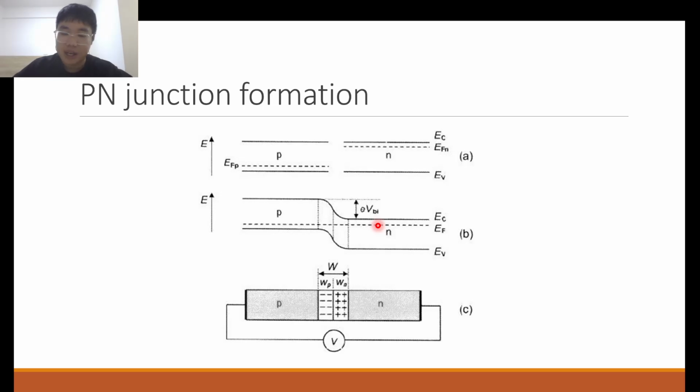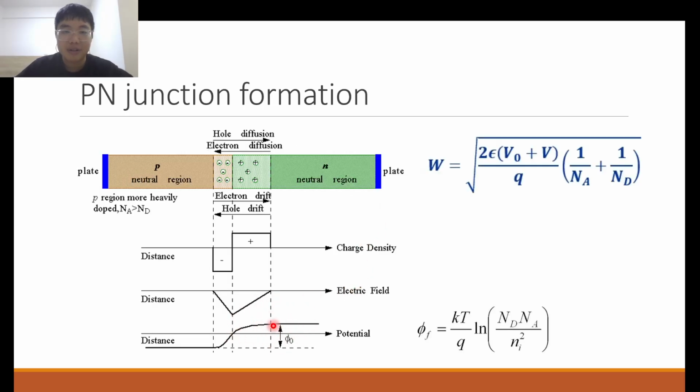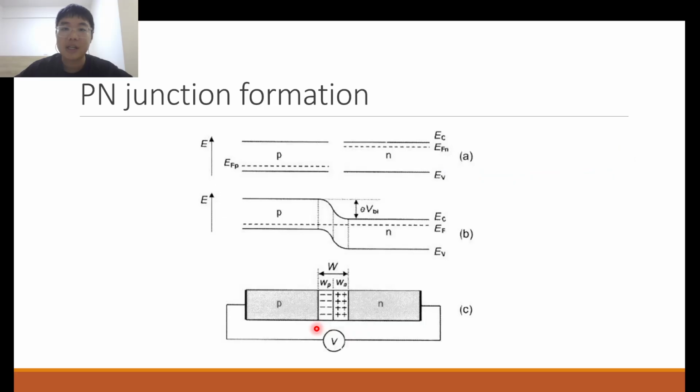And so we get exactly the inverse of this graph over here, but that's simply because of the definition. The N side is positively charged, the P side negatively charged. Since this is defined based on electrons, it makes sense that electrons are more stable in a positively charged environment, so it's lower in energy on this side and higher in energy on the other side.